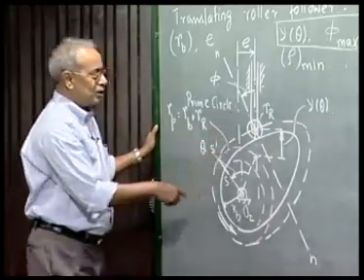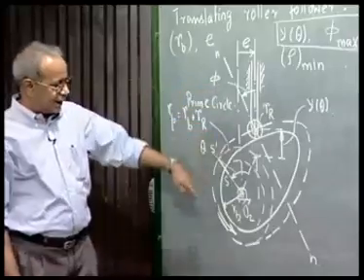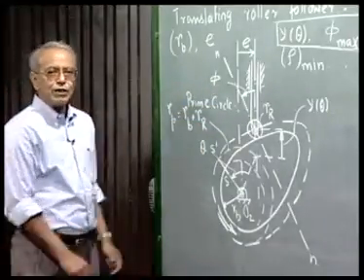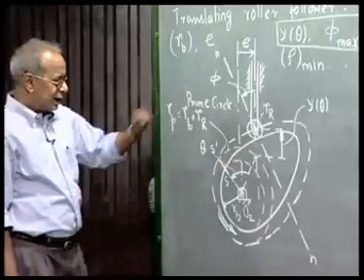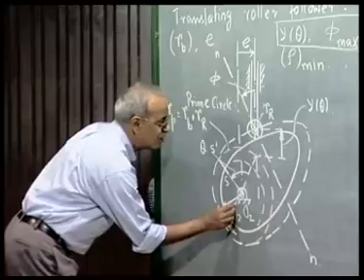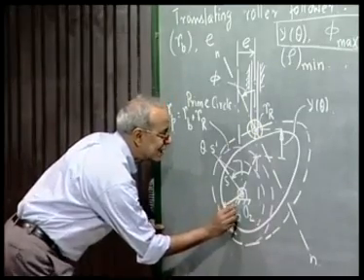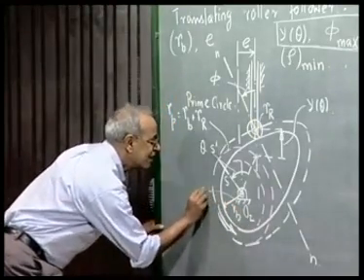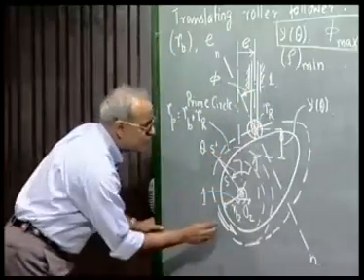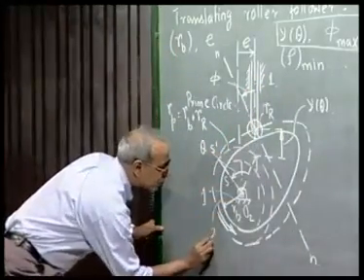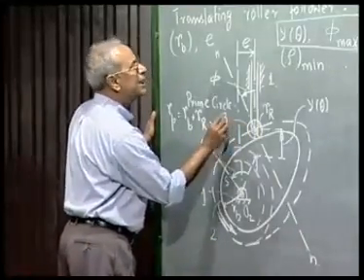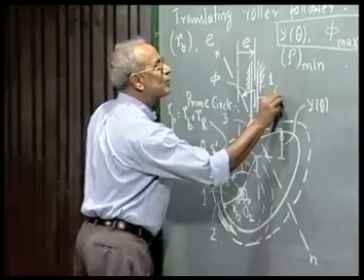Now, to determine the pressure angle in terms of these geometrical quantities, I take advantage of the Aronhold-Kennedy theorem. This is a mechanism, as we see, of 4 rigid bodies. The fixed link is 1, the cam is 2, the roller is 3, and the follower is 4.